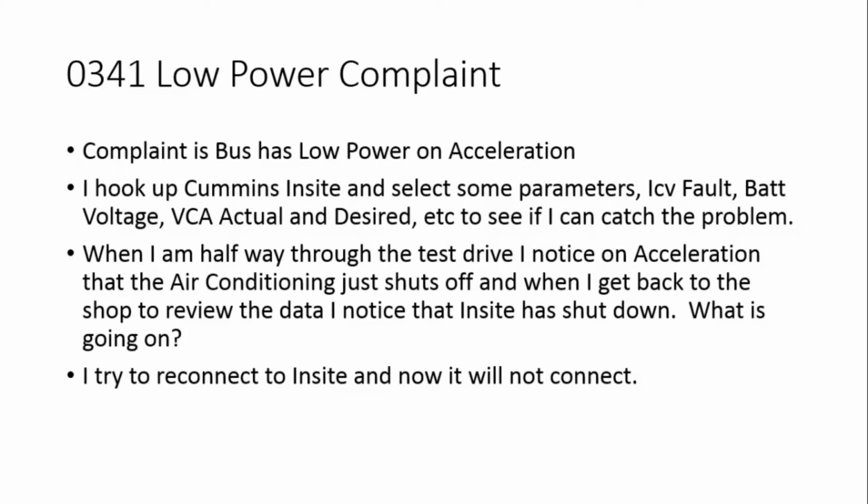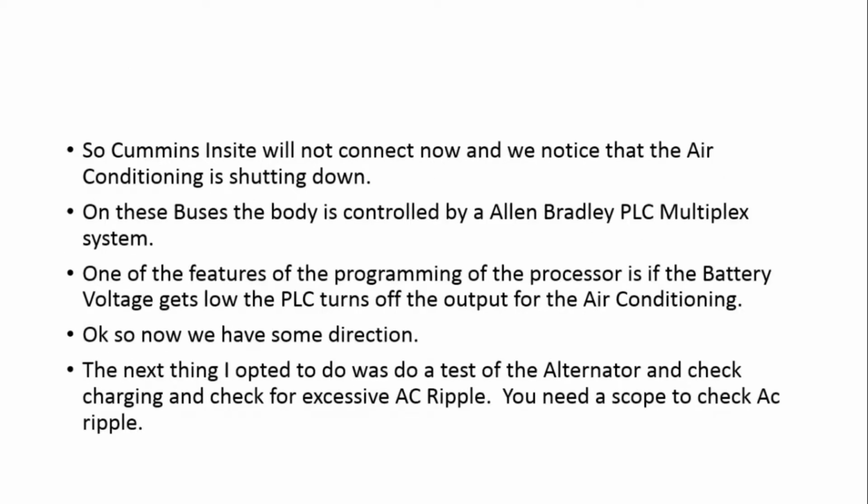So now I'm putting it together. I'm not able to communicate with the scan tool with Cummins, and I also noticed that the air conditioning shut off while going down the road. So I know where this is going now, and when I get to the next slide, I'll explain why.